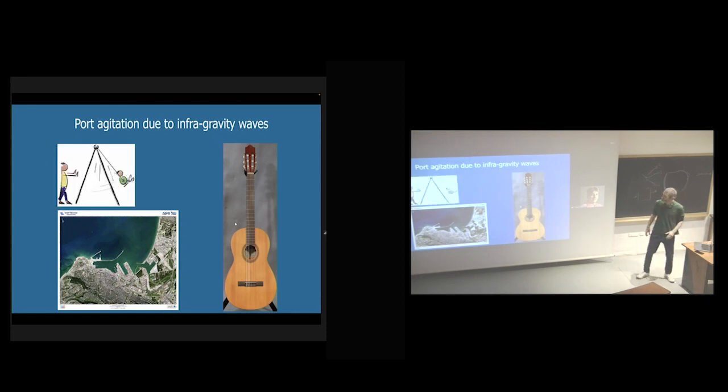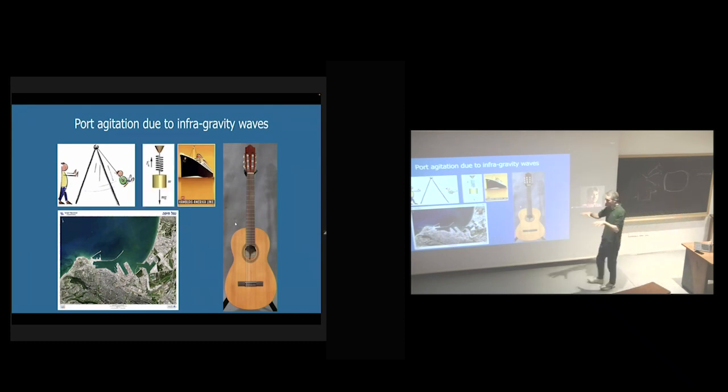If you think about a ship, that's like a resonance situation. You push the kid, and you do it a lot when you start being a young parent, and then you think about resonance because you are a scientist. The same thing happens with the ship inside the port. The ship, if you think about it, is a mass and spring, yeah? You push it down, it will jump up. It jumps up, it falls down, yeah? So it has natural harmonics.